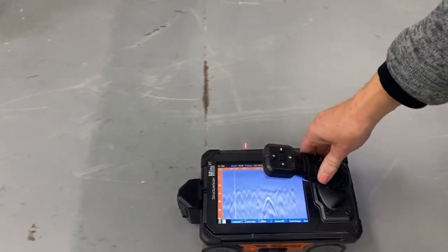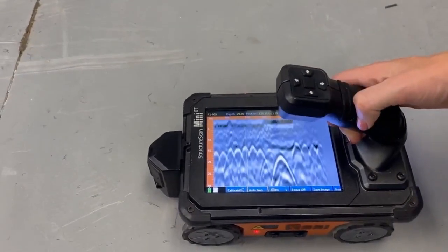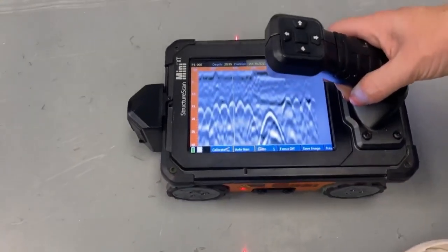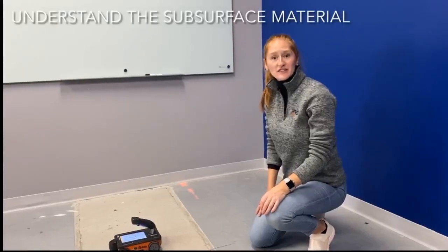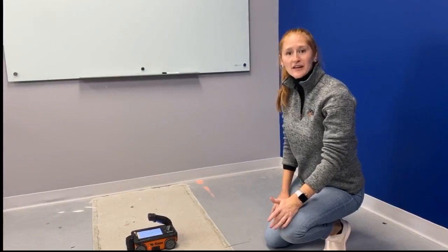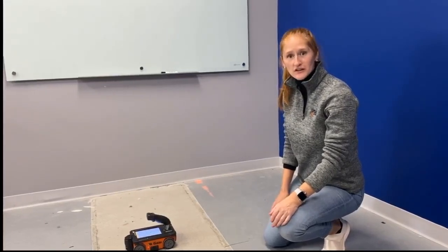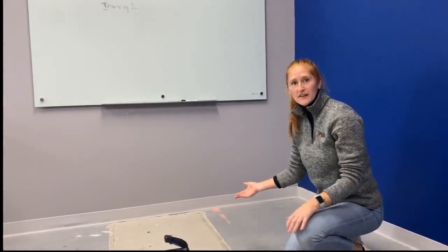We use the backup cursor, which is the yellow line on the screen. I just auto-gained the screen, which made the targets brighter. The type of surface that we are working with is slab on grade. Slab on grade is concrete poured over dirt, and you can tell there is a trench that was built, most likely for a pipe.